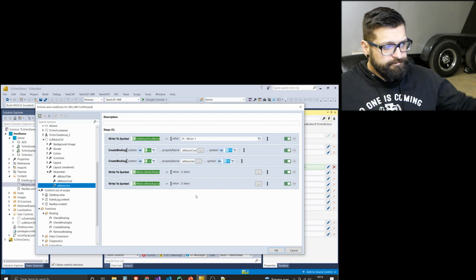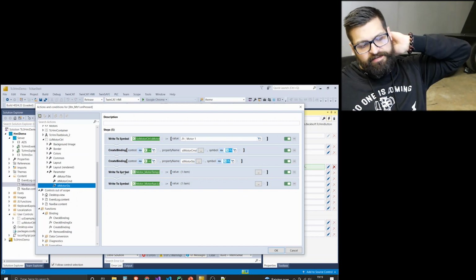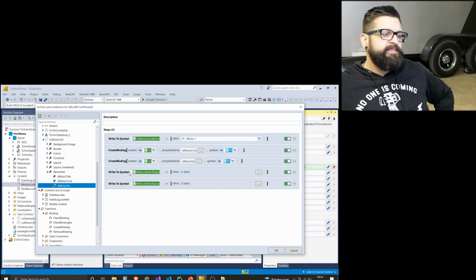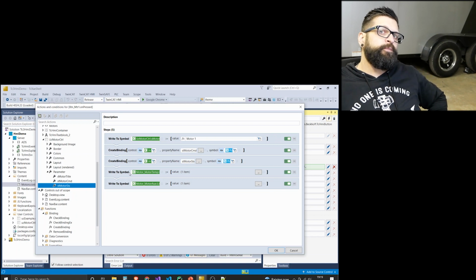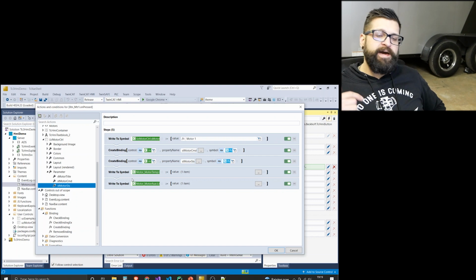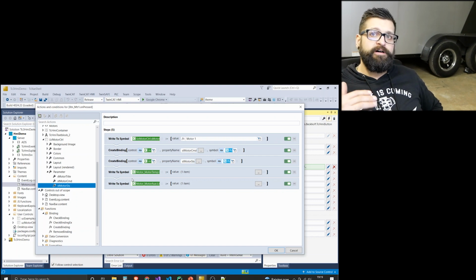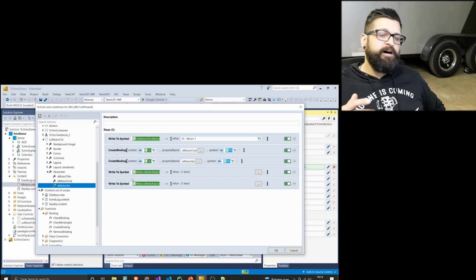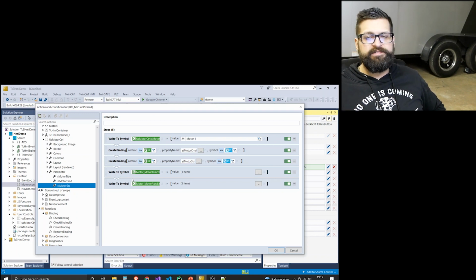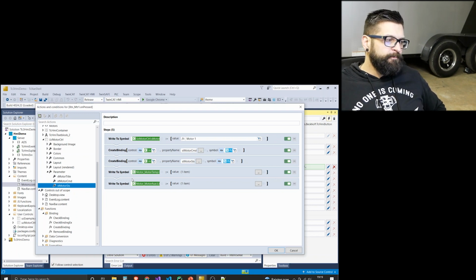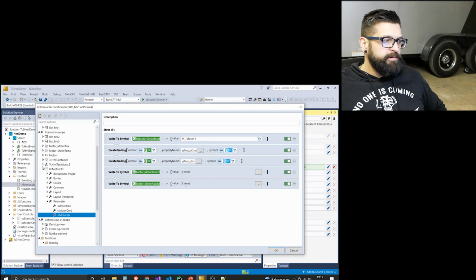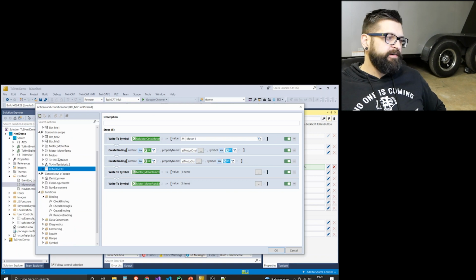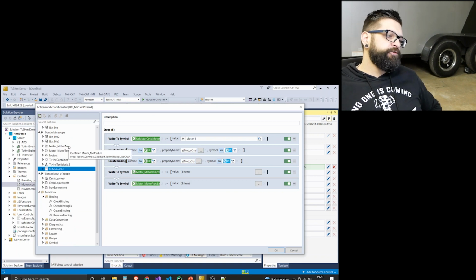The next two, what I'm doing is a little bit deeper. It's in the trend line charts, and that's passing in the correct data set that I want on the trend line chart. So obviously when I click motor button 1, I want to pass in the temperature for the temperature chart of motor 1 temperature. For the aux contact state, I want to pass in the aux contact state of motor 1. And so what I've done there is I have, again, in my dropdown, I look at my controls in scope, and I see I've got my trend line chart from my motor aux, and I've got my trend line chart for my motor temperature. Drag and drop those over.